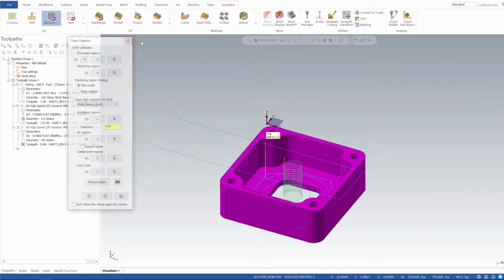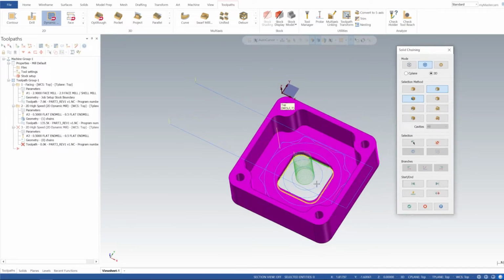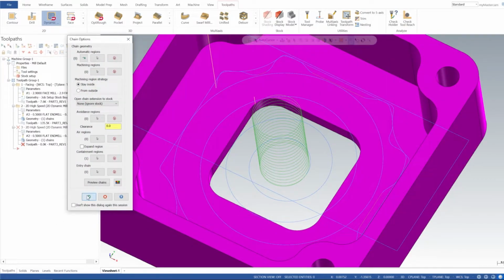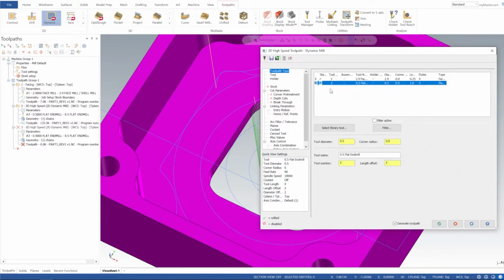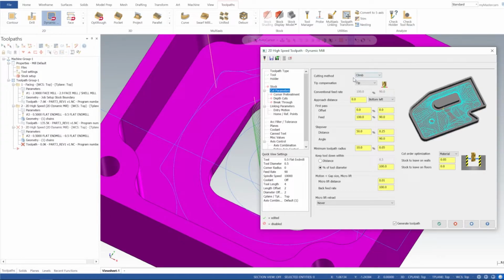And then I'm going to select another dynamic mill. And same thing, we're going to stay inside and containment region. We're going to select the inside pocket of the inside pocket. All right. We'll select OK on that. We'll select OK. Tool, same thing. 1/2 inch end mill. And we're going to do 10 grand at 90 and 90. So all this is going to be the same information as we left on the last one that we did.